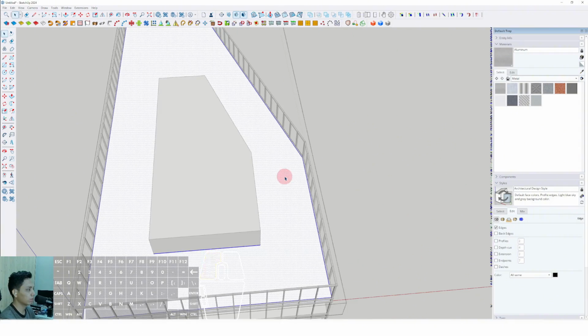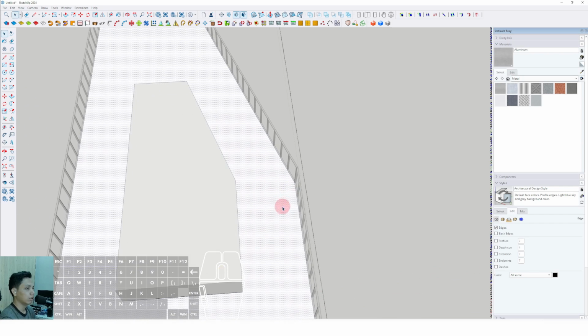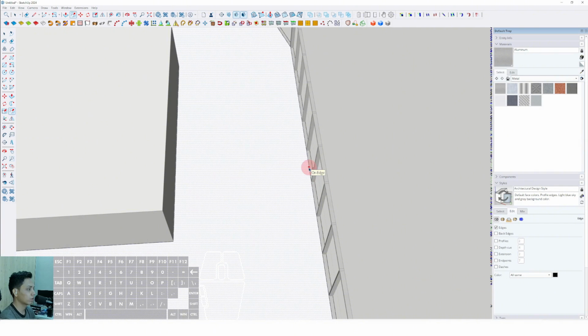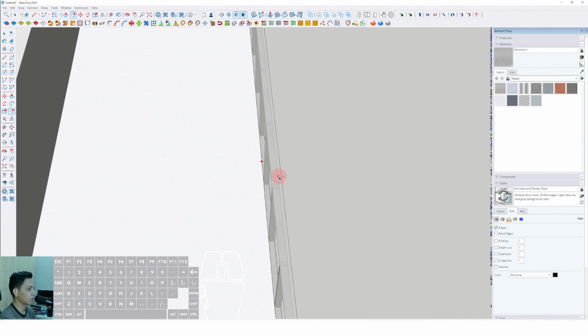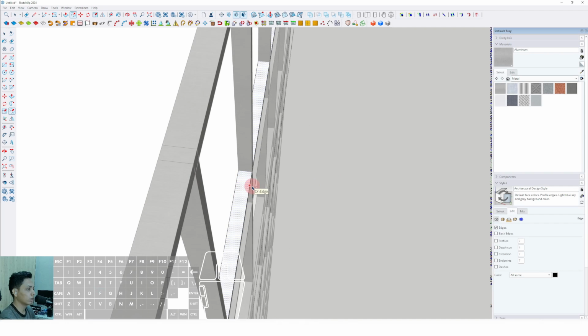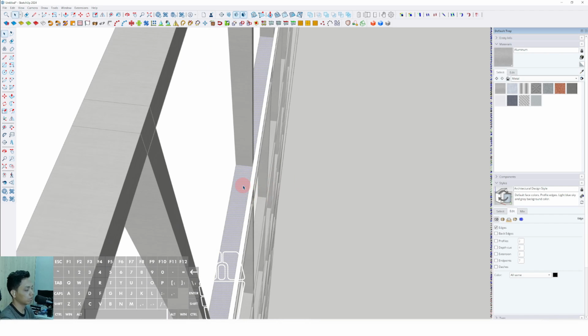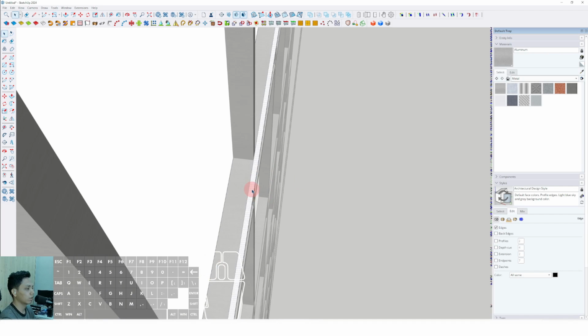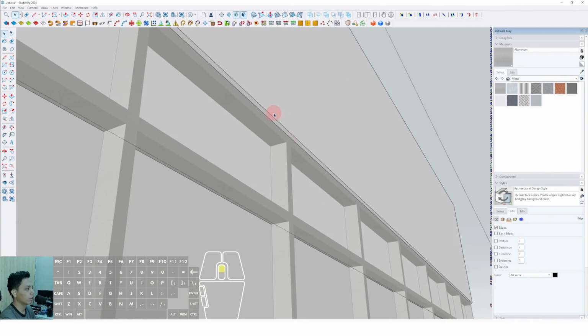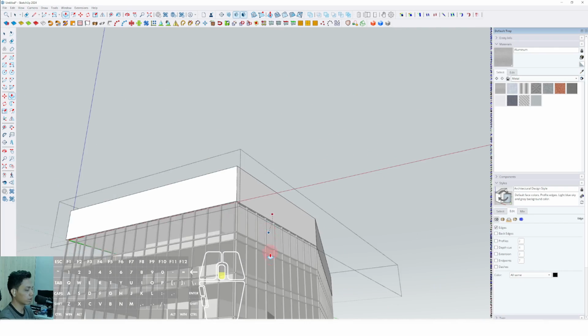Then just select this top surfaces of this vertical building. Then we can select offset tool, click on this edge, offset to the outside, okay, and click this edge again, offset again, offset to this outside of the curtain wall frame around 50 millimeter approximately for the glass thickness. Okay, then we can adjust for the glazing system on this high-rise building.